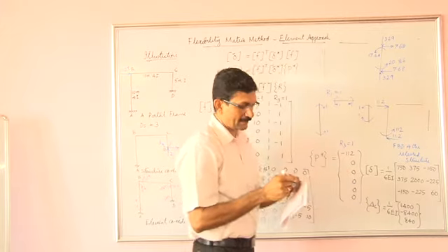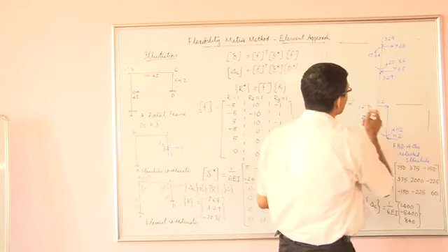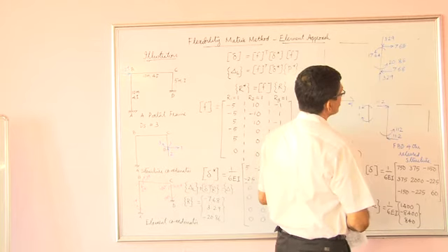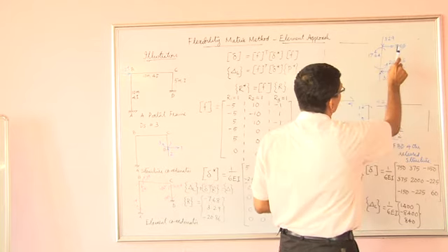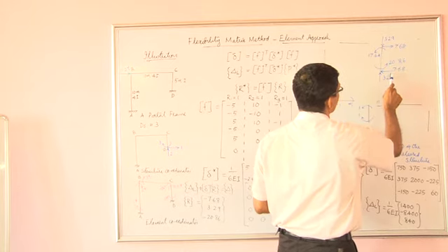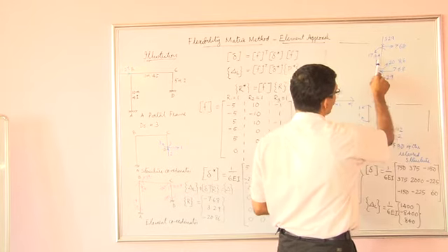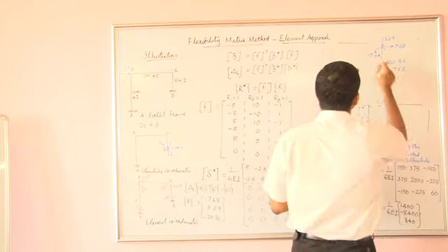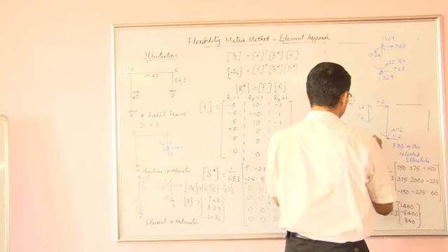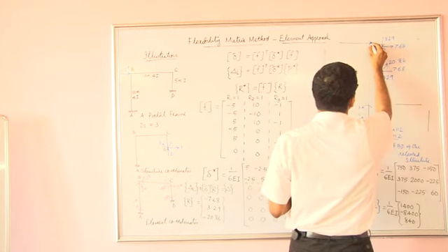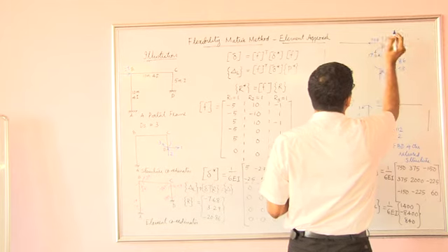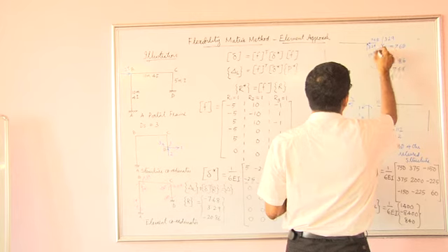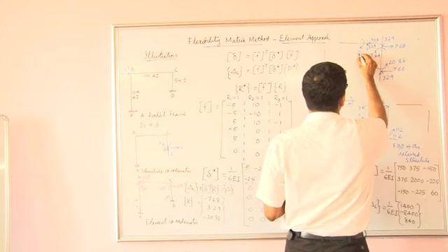So if you apply the condition sigma m is equal to 0, to equilibrate this moment you require a clockwise 20.86, and for equilibrium of 7.68 into 5 you require another moment. The sum of those two would be 17.64 over here. Now further, if you proceed for the equilibrium of this beam, this force is 7.68. There is a vertical force of 3.29. Clockwise moment of 17.64.